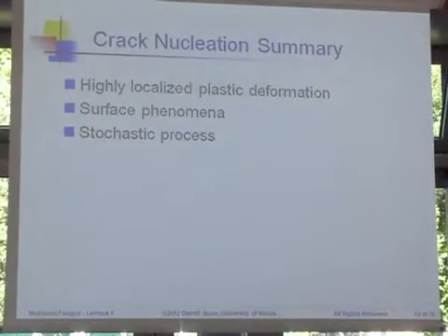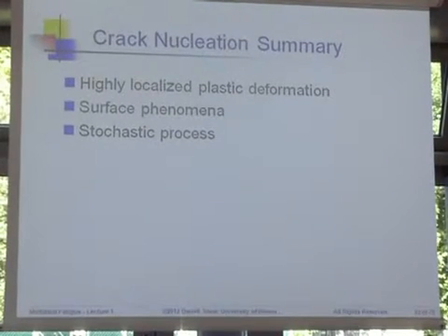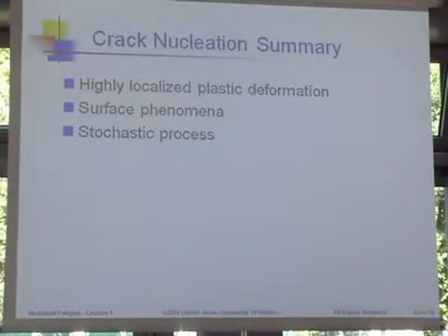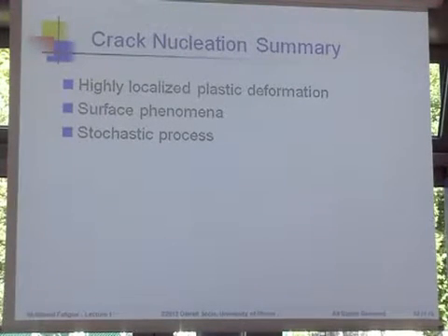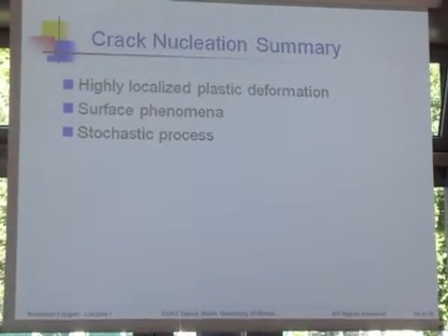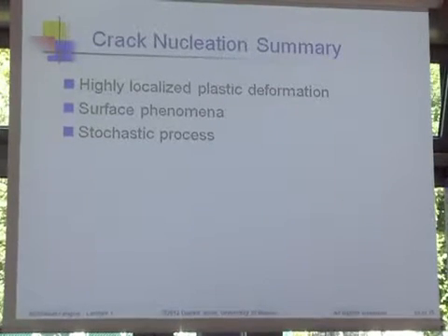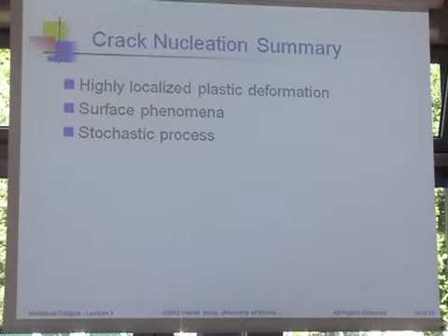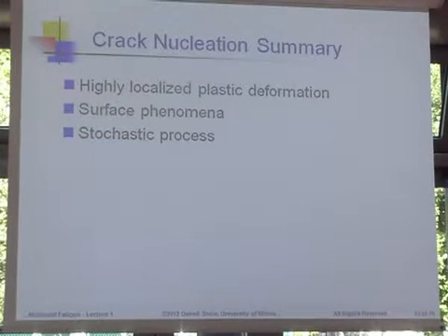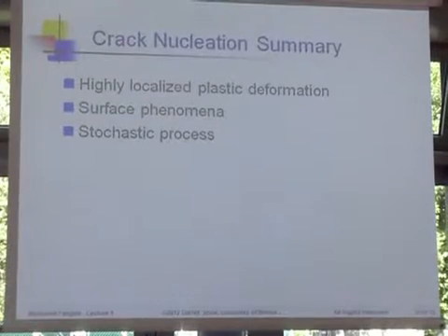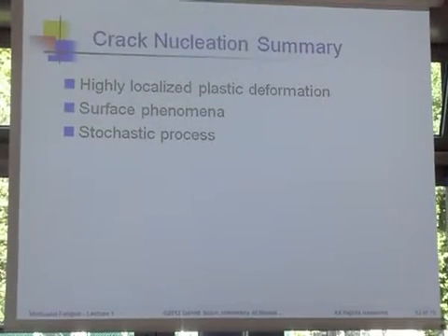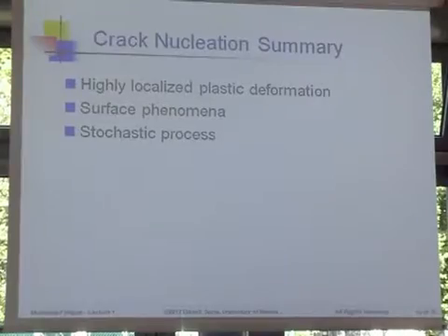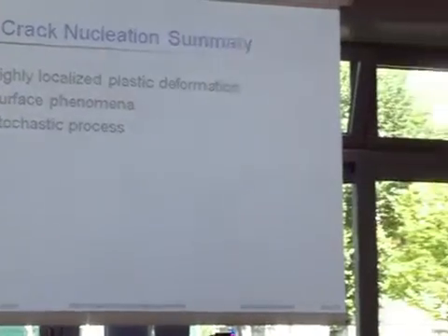So let's just summarize these ideas about crack nucleation. First of all, it's a really highly localized plastic deformation that causes fatigue. And by and large, it happens on the surface. Now, I need some special definitions of surface. I have no problems with the surface inside the material. Well, why is that? I just think about a bimaterial. So I think about a shaft which has been hardened only on the outside. There's one material on the outside and one material on the inside, and so I think about a surface between the two. So if you allow me to have that definition of surface, fatigue happens on the surface.